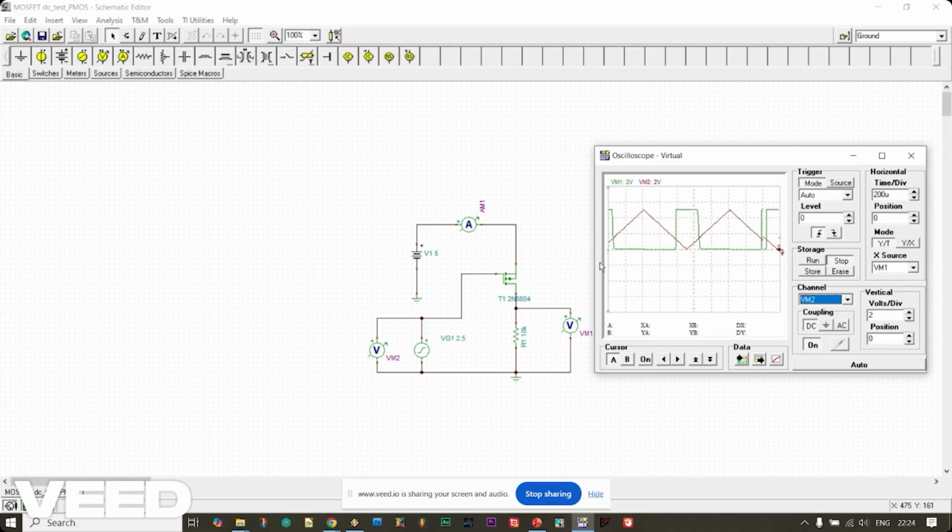So here you have 5 minus this voltage. 5 minus the triangle wave. That is the circuit here. So here it will be high. This is a turn on. So there is fast switching. It turns on quickly. Off to on goes rapidly, and on to off quickly.